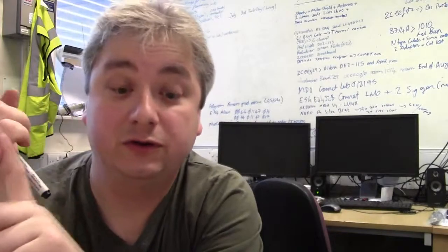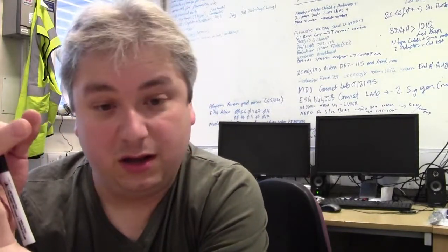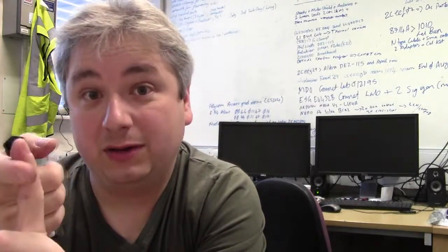You got carbon film, metal film, carbon composition. You got wire wound. You got different combinations of the actual shapes. You got wire wound, heat sinked wire wounds. You got wire wounds in ceramics, or ceramic wire wounds. They used to be called, now called ceramic wire wound. You got wire wound on silicon. You got metal oxide. You got your box standard wire wounds.